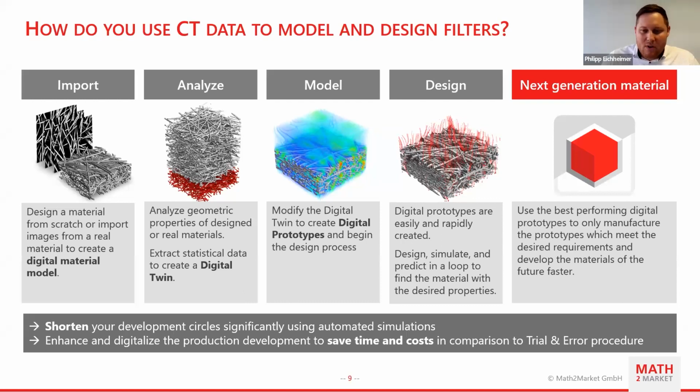But as we already mentioned, for optimization studies we need an optical or digital twin. If you're a manufacturer and you know all the parameters like porosities, fiber distributions, fiber lengths, and orientations, then you can directly use our structure generators to generate the structures. But if these are unknown, we have to rely on micro CT or structural images in general.